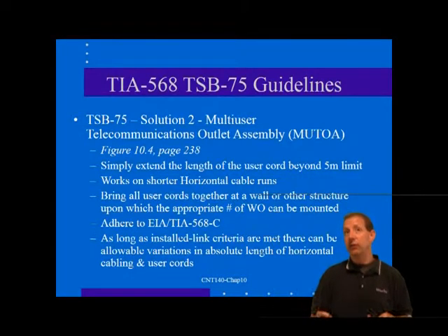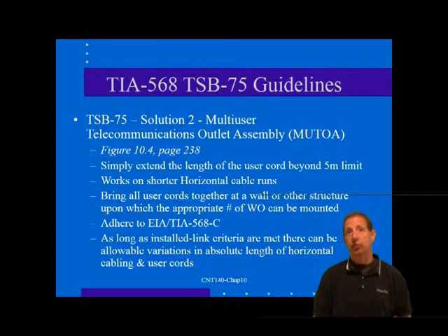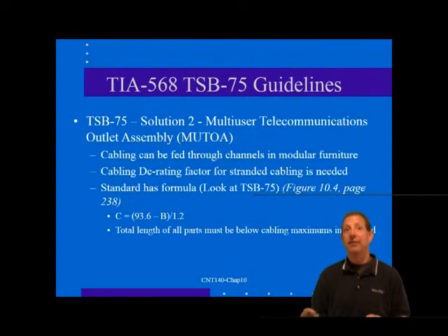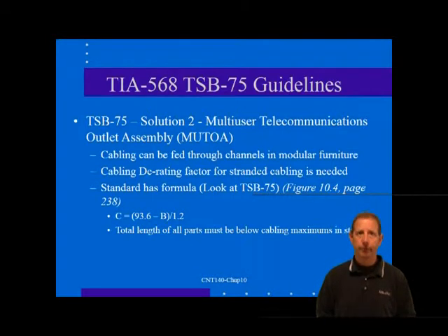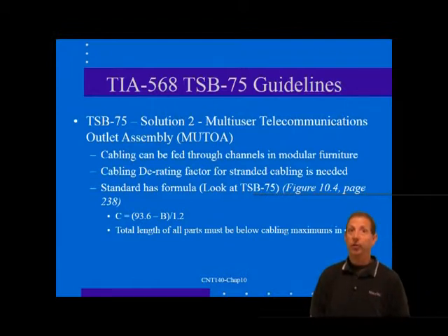The cable raceways in modular furniture normally have removable panels along their length, so the only difficulty is to run the connectorized cable ends through the openings in these structural columns placed for this purpose. Care should be exercised in this process, as there is ample opportunity to bend, kink, or cut the cable during the installation into modular furniture. Some of these removable panels are constructed of metal, so the installer must also be cautious of sharp edges.